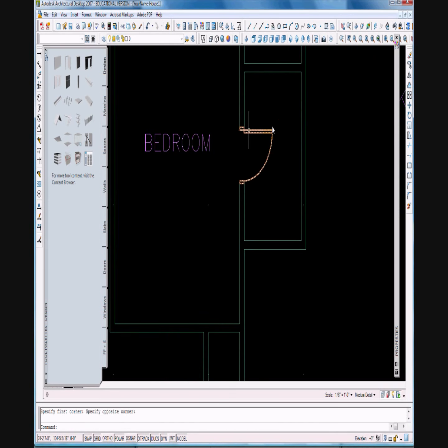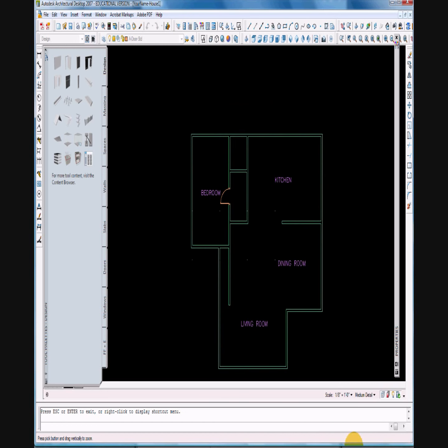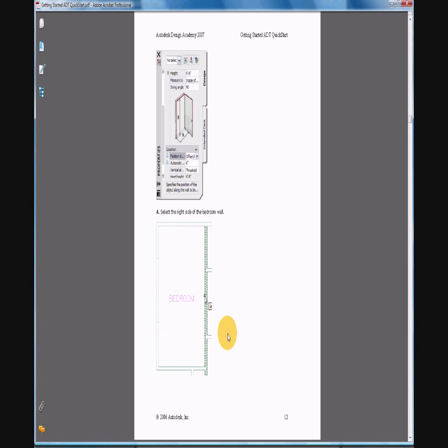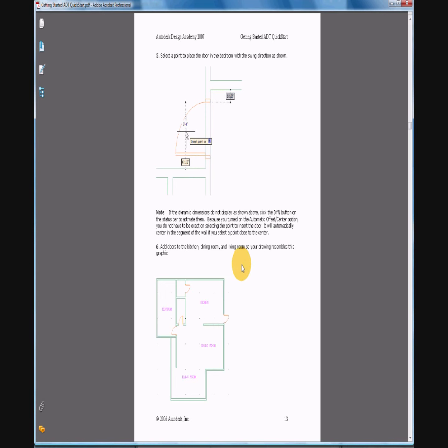So I'm going to go ahead and zoom in on the door. Select the door. And if you click onto it, you can see there's arrows. And if I select the arrow, you can see how it will move in the opening I want. So if it opens to the left or the right, swings out or swings in. And to get out of that, just hit the Escape key when you're ready to move it. I just zoomed out. Alright, so let's move it to where it needs to be. On my PDF I can zoom in on the file to look at it more closely.